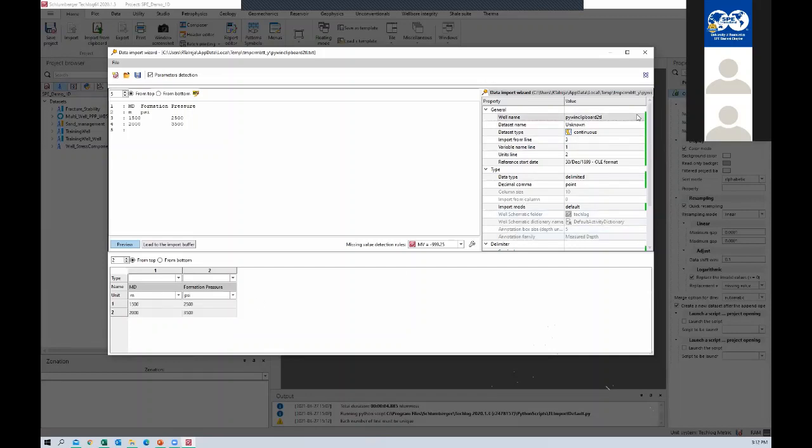Now on the top right, you need to select which well it belongs to, right? You need to load well data into a particular well. This MDT might have been recorded in a particular well, so you need to select which well it belongs to. You can give a name to the data set, the name of the file, like this is an MDT data set. I gave MDT data set. You can define its type. There are a lot of other things that you can do.